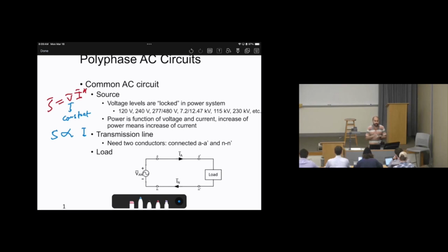Then there is an ampere capacity. So there is some current limit for each conductor that we cannot exceed. As I mentioned, in a residential home we have 20 amperes or sometimes 30 amperes. You can also imagine this as water pipelines. If there is a large demand for water, you need a larger thickness, right? Replace that pipeline with a larger one, increase the radius, then you can have more water. Or you can install another water pipeline to supply your demand.